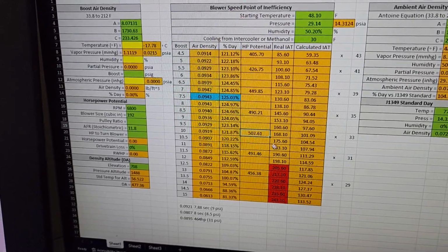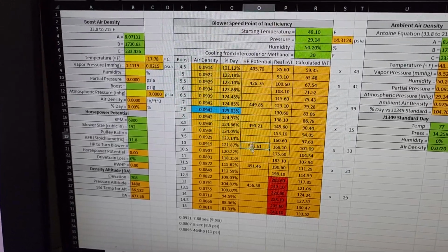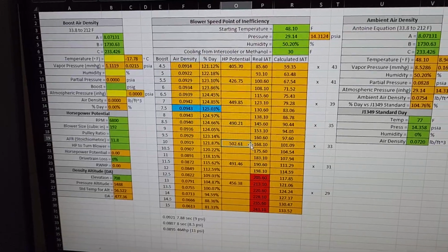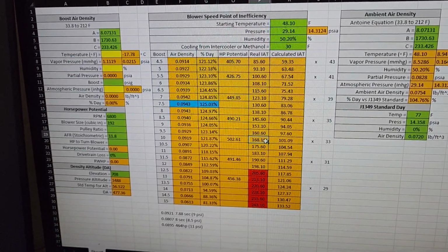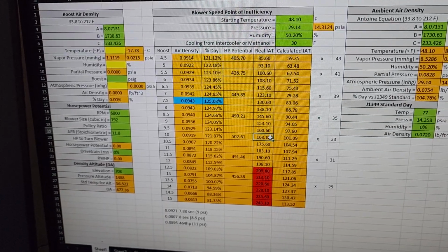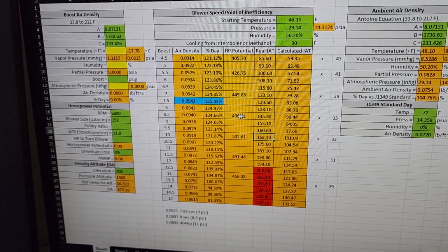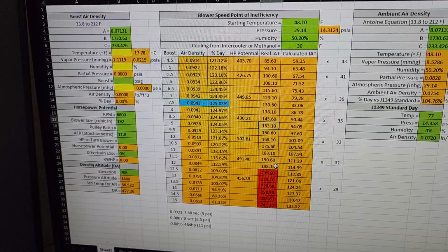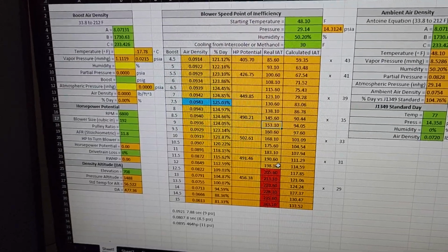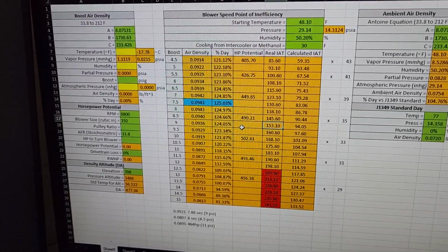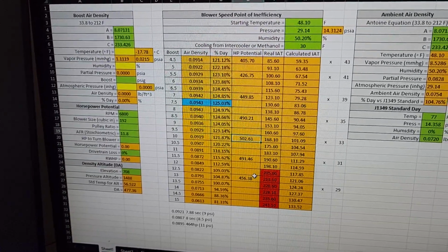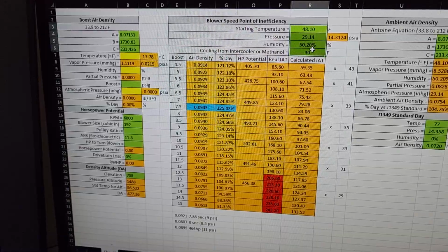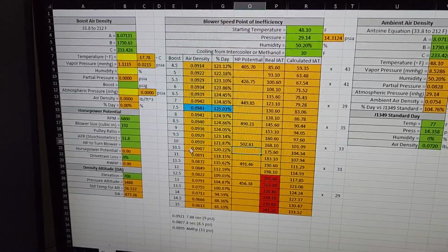But anyway, so this is just my specific supercharger, and discharge temperature of 168 degrees. You know, I saw on that 9-pound run an average 155 or whatever, 156. So this was pretty close. So yeah, I should be able to meet my 500 rear wheel horsepower goal depending on the air density the day that I do the run and which pulley I run.